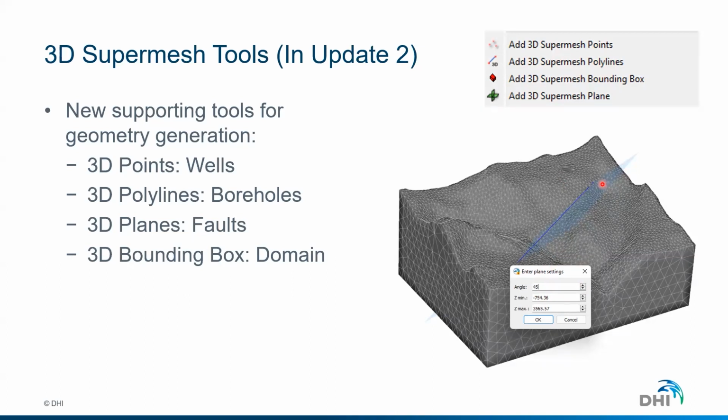There are many cases here in geothermal modeling happening now in Germany. People wanted to simulate inclined boreholes. So you can draw your own trace of the polyline directly into FEFLOW without the need to use external software. Bounding box is something quite interesting. You can pass a set of surfaces which do not close a volume, and FEFLOW has a methodology to identify the bounding box, and we create a 3D volume for you so that you are ready to go for the meshing process. And the plane is what I just explained.